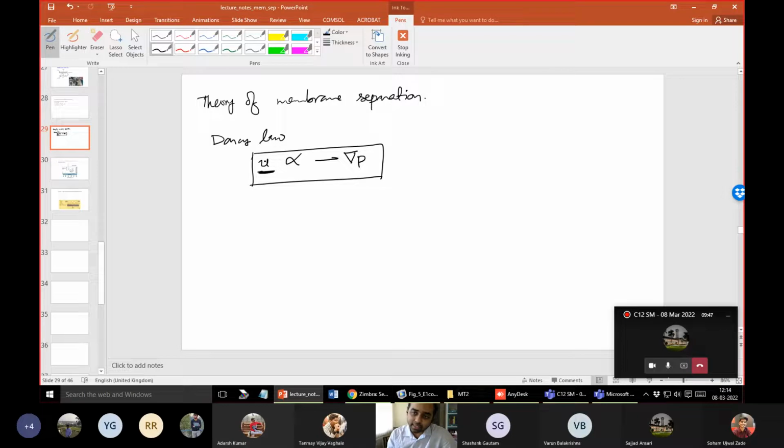So in this small region, instead of the pressure gradient, or trying to find out how pressure changes across the thickness of the membrane, a more practical way to write this is delta P divided by the thickness of the membrane, right? So what is this delta P? Delta P is just the arithmetic difference across the two sides of the membrane, and you divide it by the thickness of the membrane. So instead of writing a gradient, we just use this sort of finite difference approach, because the thickness is really small for this domain, right?